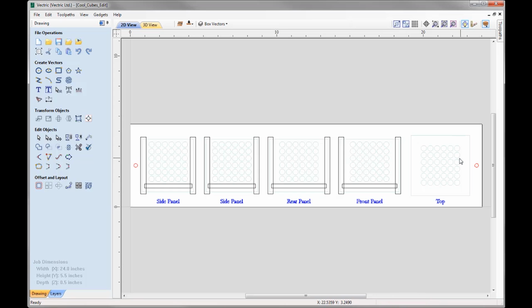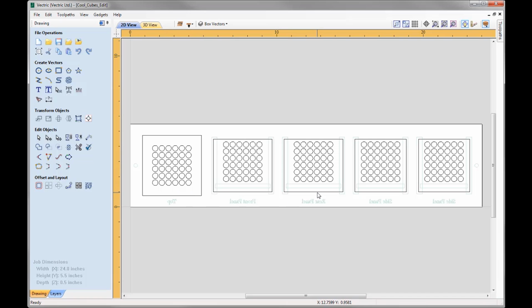We're going to cut all the way through the material, and we're going to cut into the spoil board, where we'll then take our material off as we've finished with the top side, and then we're going to put the dowels into the spoil board. Then when we flip our material over, we're going to align it back in X and Y into the position, secure the part in place, where we'll then go and run the toolpaths for the bottom side. I'll look at machining all of the decorative elements, followed by profile cutouts to cut all of these panels out. So let's go and run these toolpaths.